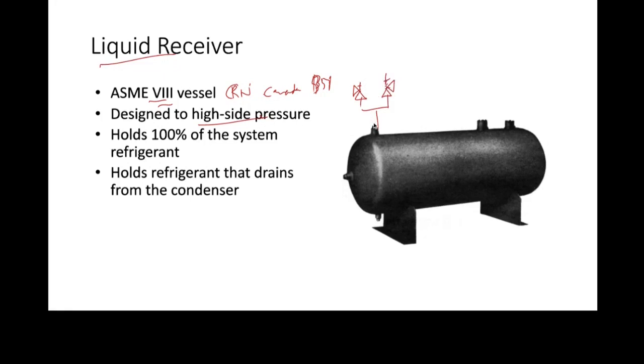These pressure relief valves are not going to have tri-levers, so you can't test them. And what we will have is basically a three-way valve. It's one of the few places where it's permitted, but the three-way valve will select either one valve or the other one, so we can take the valve off. Because they don't have tri-levers, we actually have to get them tested, recertified, or replaced every 5 years, according to CSA B52.